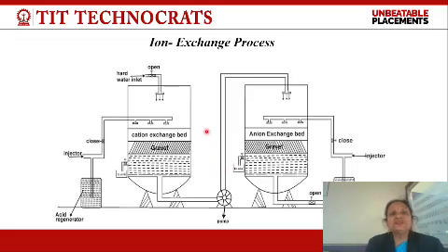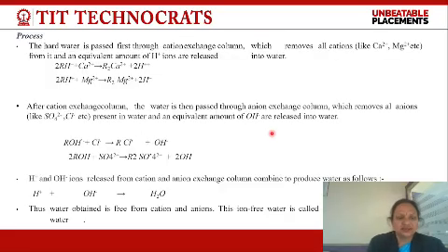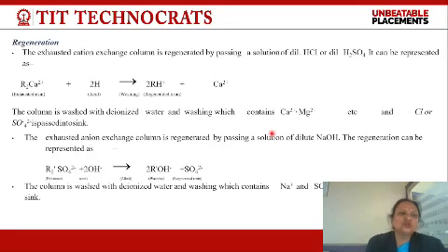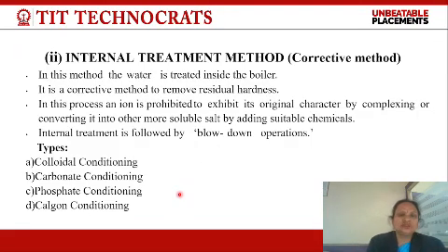In the ion exchange method, we use cation and anion exchanger beds, and both the cations like calcium, magnesium and anions like bicarbonate, chlorides and sulfates are captured here, and now the resulting water is pure soft water, and after washing these instruments we can again use them for further processes.